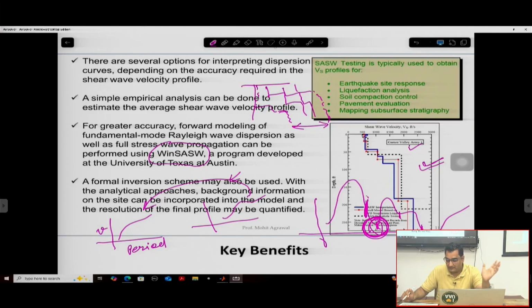Now there is an uncertainty part of it. Let's suppose you have computed your model and you have come up with a shear wave velocity model. It may also be possible that there might be other models that also explain your data well. So those are equally acceptable models apart from the best fitting model that you have just searched for.